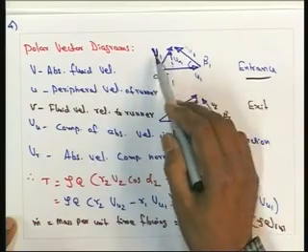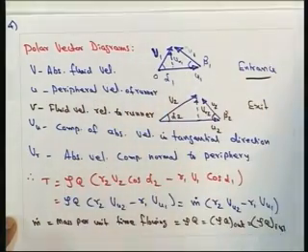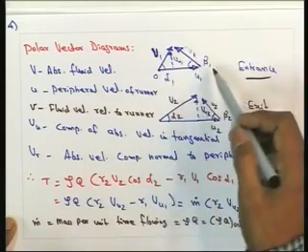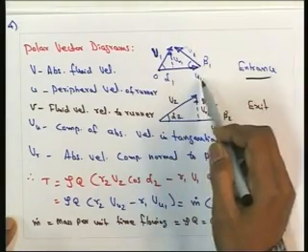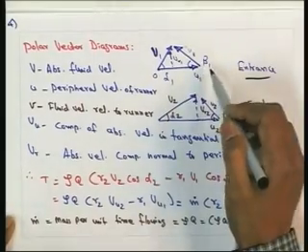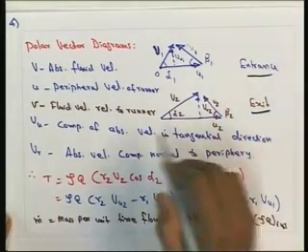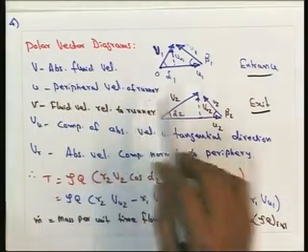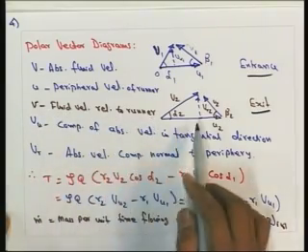V is the absolute fluid velocity, U is the peripheral velocity of the runner, which is what we consider here. Subscript 1 indicates the entrance, and subscript 2 indicates the exit. Small v is the fluid velocity relative to the runner.